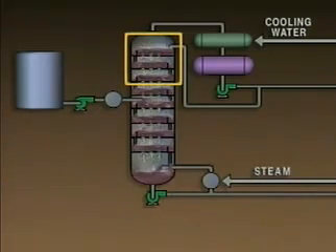On the other hand, if the temperature at the top of the tower is lower than it should be, less of the lighter components will vaporize. Some of the lighter components will remain as a liquid and flow down the tower.